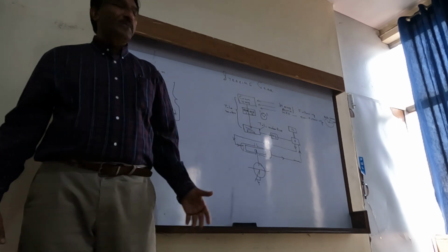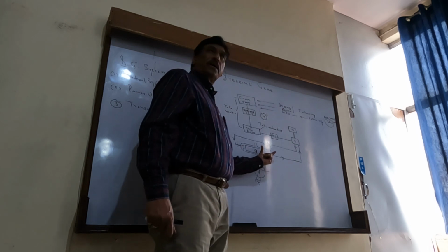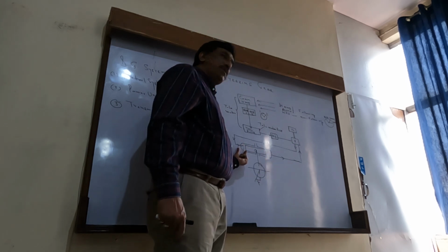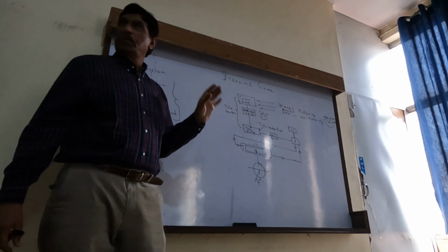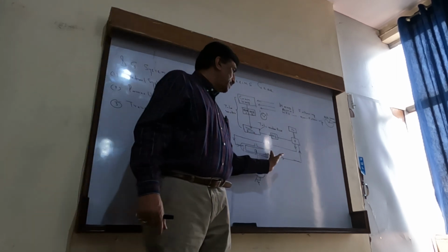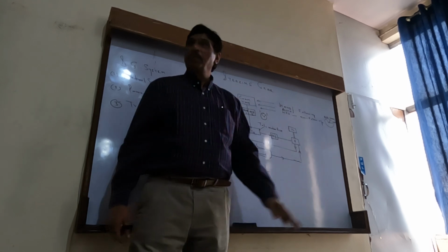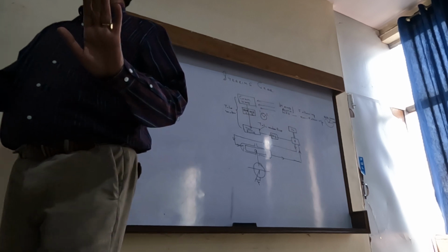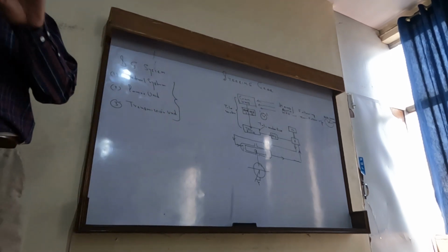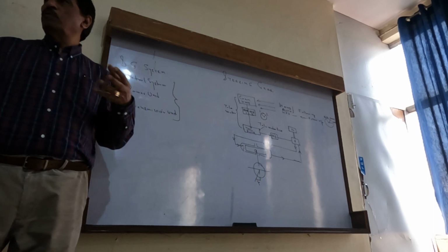One more thing we have to remember is whatever is the movement of piston towards right, that much space is created this side. That means that much volume of oil has come. Same has been displaced from this side. Same oil will go back to the pump. If pump is not working or in stop or steady condition, then there is no flow and both sides are full of oil.